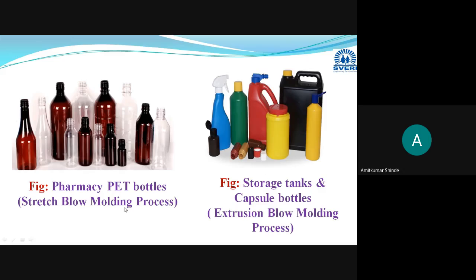Now for the stretch blow molding process, pharmacy PET bottles. This is a very important application of this PET material. PET means polyethylene terephthalate. The pharmacy bottles for storing medicines or capsules are all manufactured using PET material by performing the stretch blow molding process.